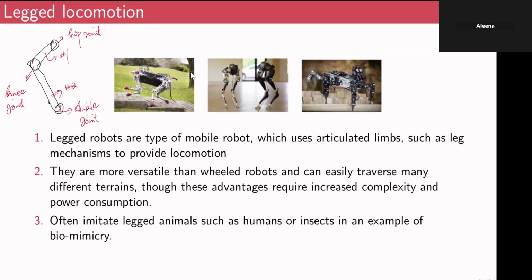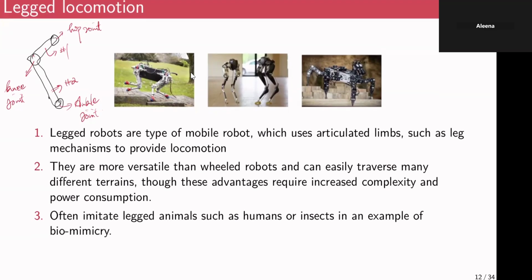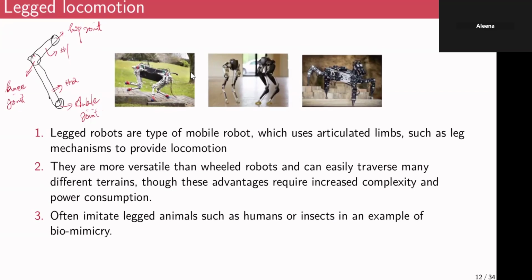And there are also additional challenges because legs are inherently unstable. And if you apply some force on these sort of robots, there is a very high chance that they may topple over. No such threats for a mobile robot, but in case of legs, you have to deal with the stability issue. But there are advantages, right? If your terrain is actually very rough or very non-smooth, or if it has undulations, legs can move through this irregular environment much more easily than a wheeled mobile robot.